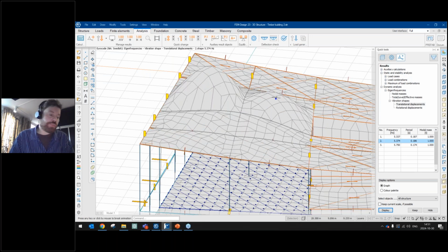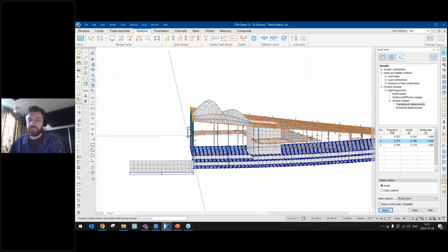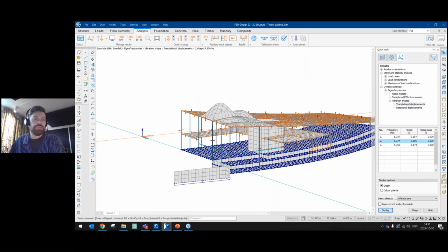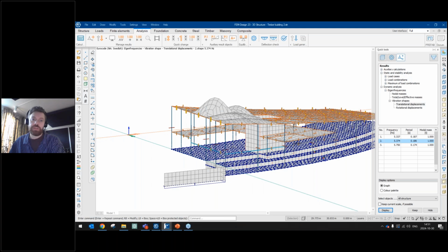And there's also something called story fundamental frequency, and that's calculating the eigenfrequency for each story in the building. That's also a very nice thing because it follows the Eurocode quite nicely, where it says that you need to check the eigenfrequency for each story basically, and that could also be carried out in the software. In this case, this structure is not really a typical story by story structure, so I haven't defined any stories, but I could possibly define a story here and a bottom story and do an eigenfrequency calculation for each individual story.